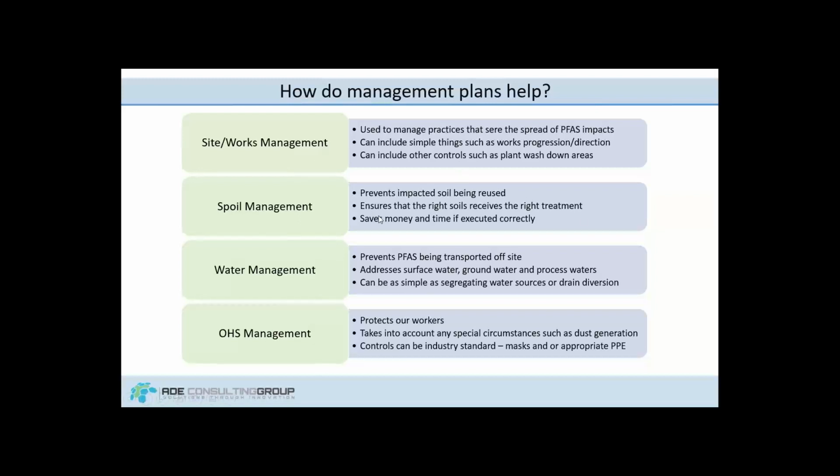Further to that, spoil management. Adequate spoil management stops impacted soils being reused. And unfortunately, in Australia, we've seen a number of cases where impacted soil has been reused, and then those sites have subsequently needed to be remediated. Ensure soil receives the right treatment. There's no point in over-treating soil. And then lastly, saves money and time. So if we know what soil is being treated where, we can really streamline our projects.